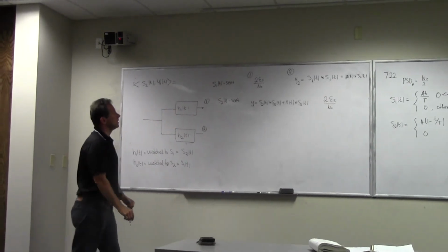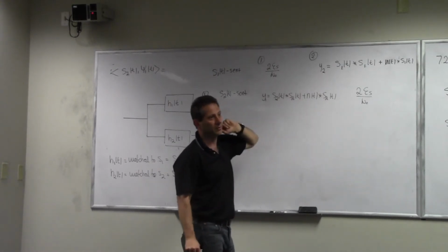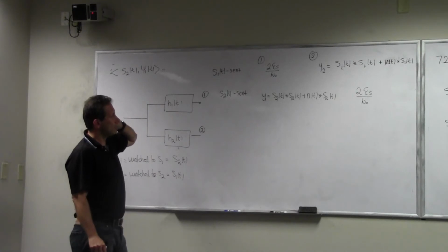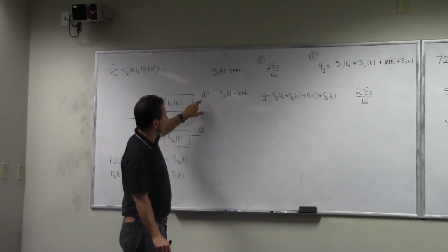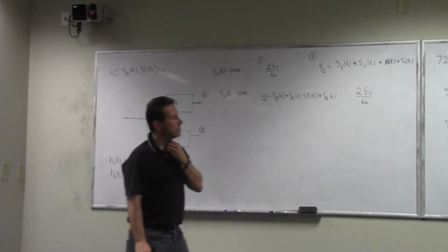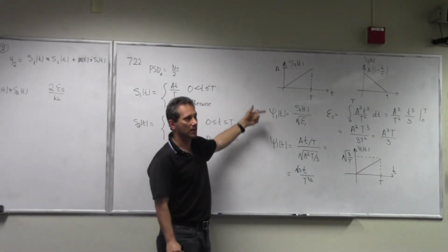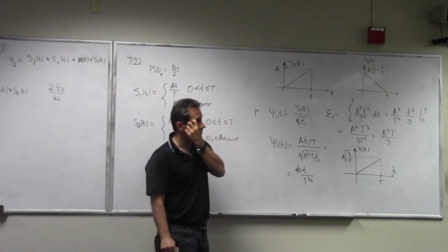Right, so now you can calculate these two and see what it is, but I'm not sure it's optimal, right? Because you may actually get substantial values here in the opposite branch. But if you do what I just started doing, we already showed that this is an optimal way. You just have your orthogonal basis, and then you have two orthogonal filters, and that's the best you can do. That's our correlating receiver.